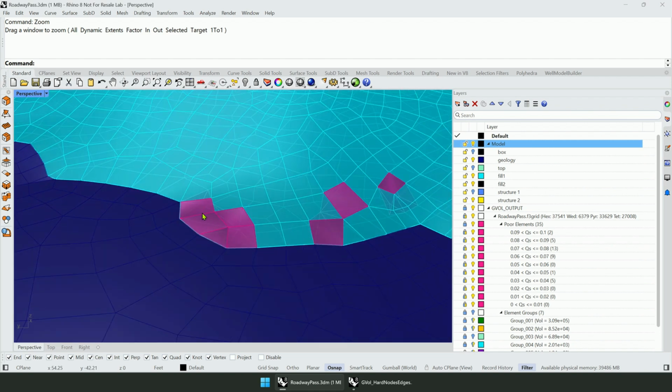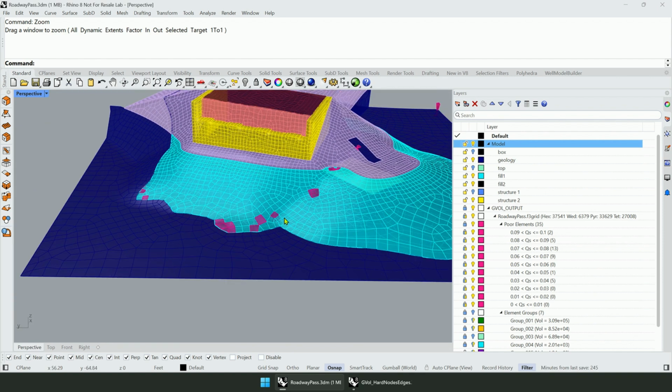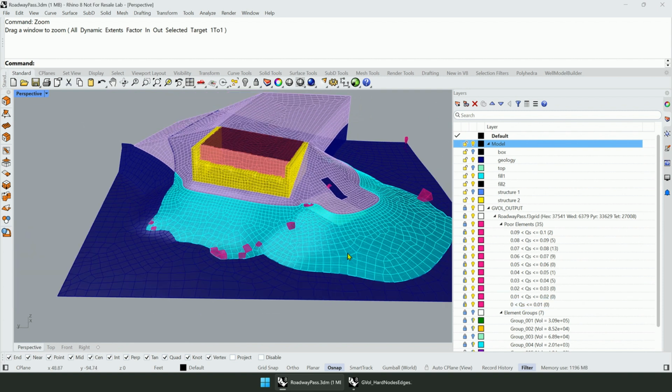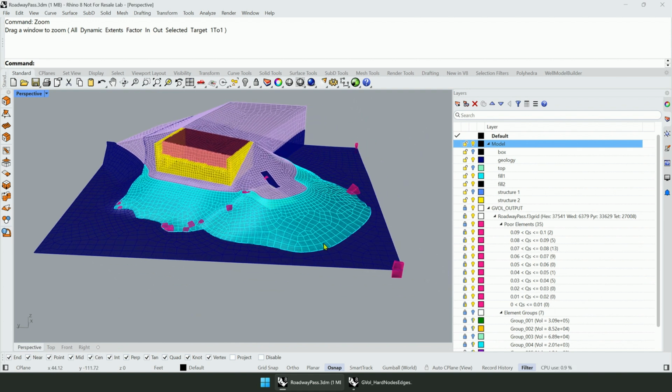So by improving input geometries, we can improve the overall volume mesh. This is an example of how you can use information about element quality to analyze your model and improve your surface meshes to create a better volume mesh.